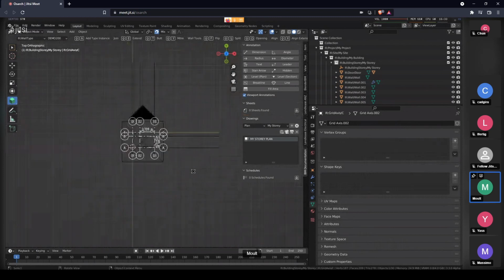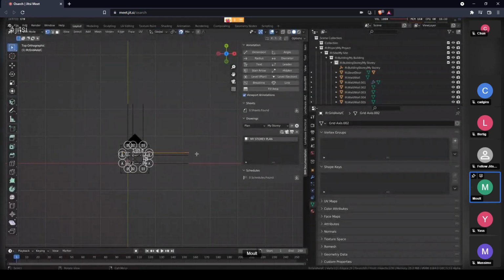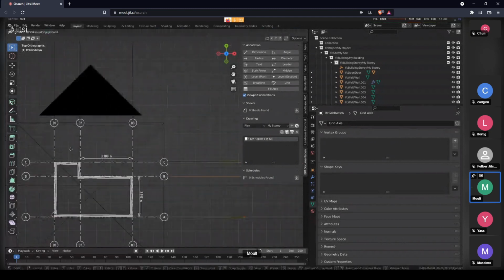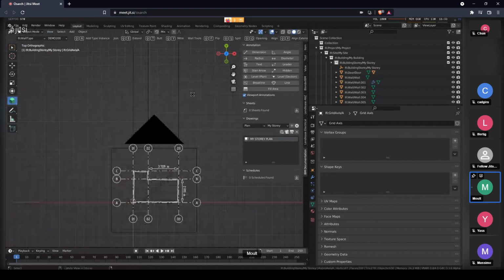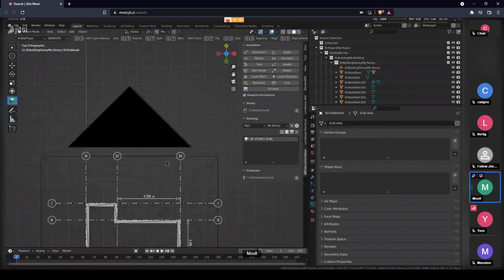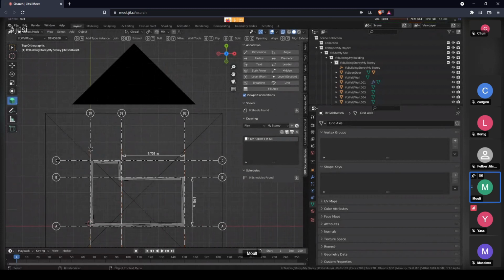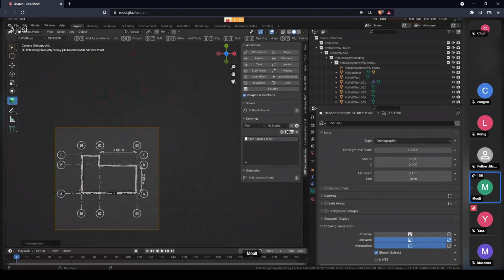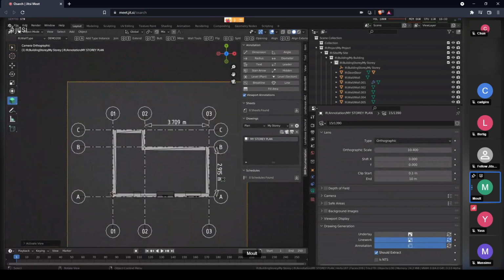But now, oops, I don't want to move that grid. Let's take my grids, fix that, and move it closer. Let's say my building is only that big. So take those three grid lines and move them in. You can see my grid lines now stop here, whereas previously they got cropped there. If I reactivate it, you can see it's auto-updated. So it auto-refreshes.